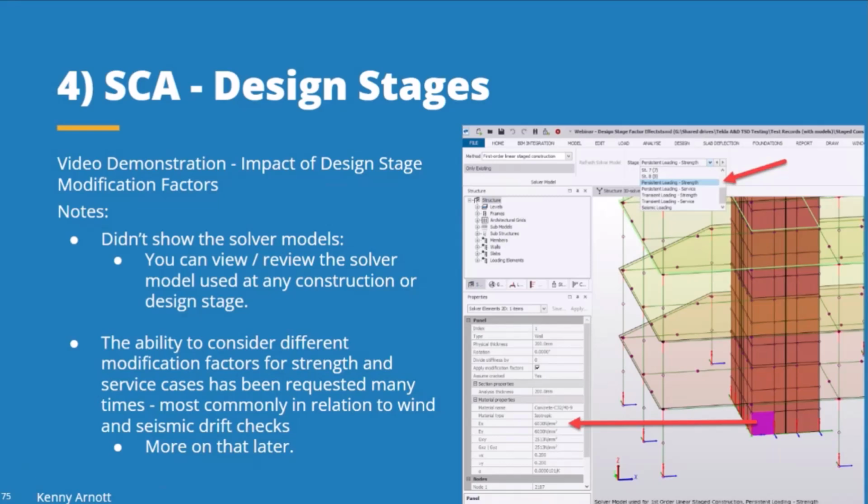They don't request it by asking for stage construction analysis, but a typical first order linear analysis has one analysis model with lots of different load cases and combinations thrown at it. This ability to consider different analysis models comes naturally from stage construction analysis. So it's an added benefit that comes from this capability.